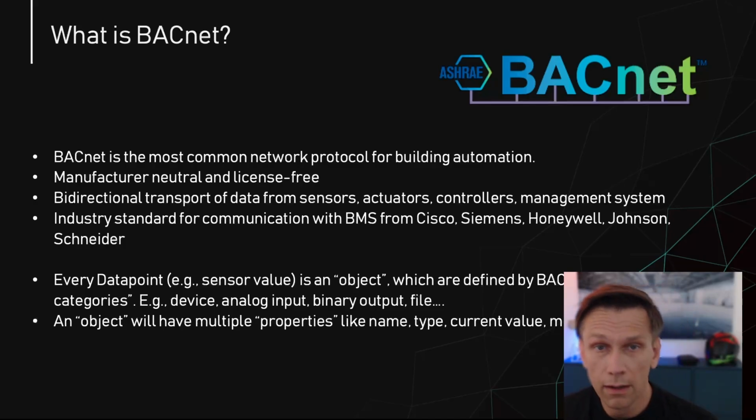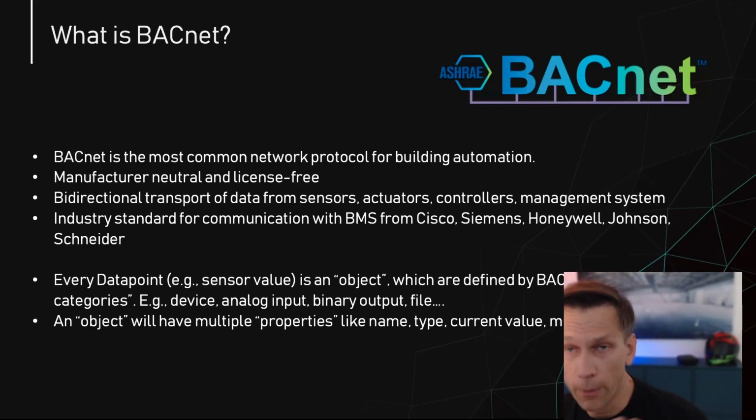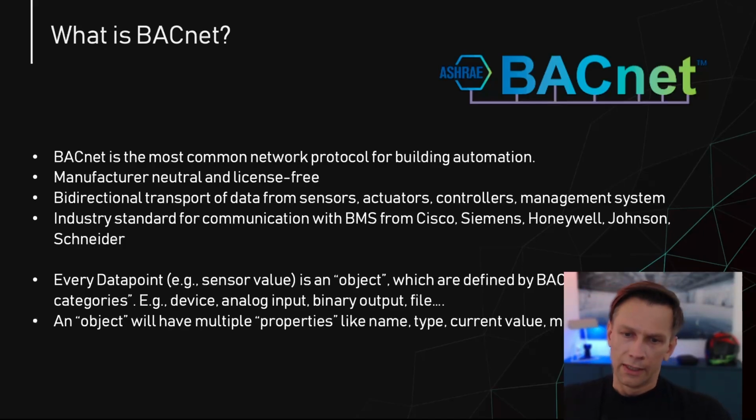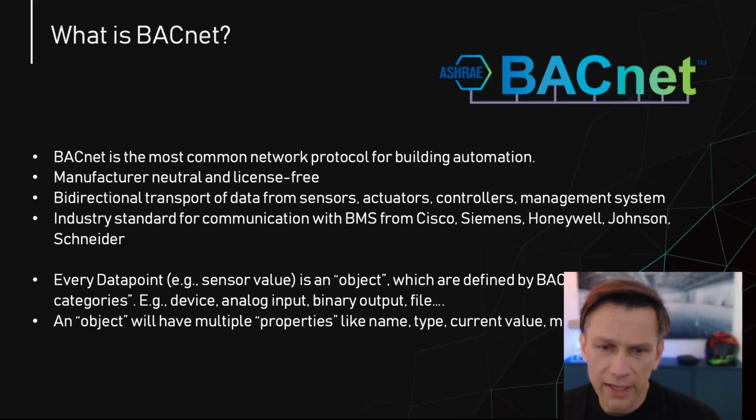If we're talking about BACnet, BACnet works with data points. There are classifications of different data points called objects, and there are more than 50 different definitions of data points. For instance, a device, an analog input, a binary output, a file, a scheduler, and so on. All these kinds of data points called objects are well defined in the BACnet standard. At the moment, I guess we have the standard 23 or 24, depending a little bit on when you watch this video. There is still progress in the development of the standard.